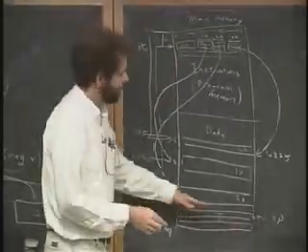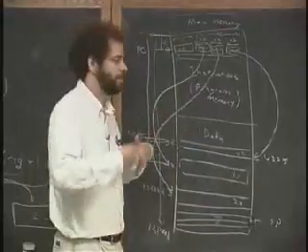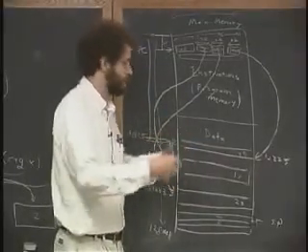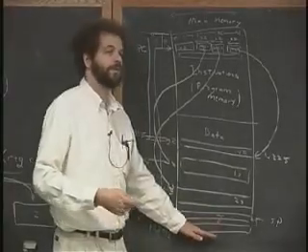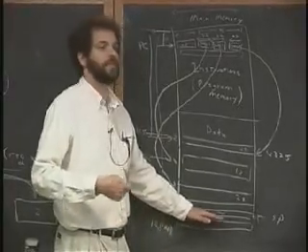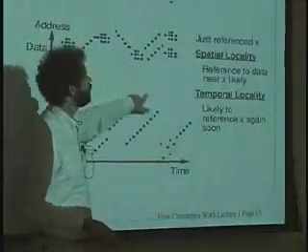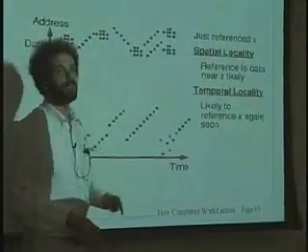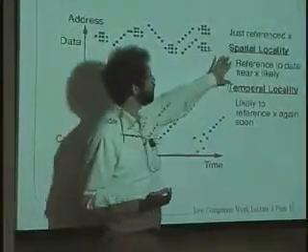And so saves, which is what they called pushes. Okay, push and save is the same thing. When we put something on the stack, we save a value to the stack, would make the stack pointer increment. And restores, or pops, would make it decrement going back down. And so you would typically see an access pattern. This is a little bit strange here, but if you saw it kind of seesawing back and forth, that would be like a stack.